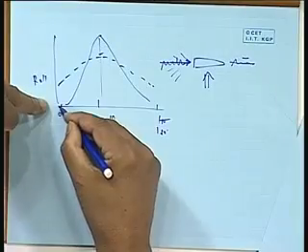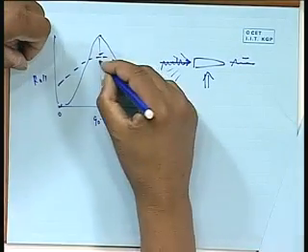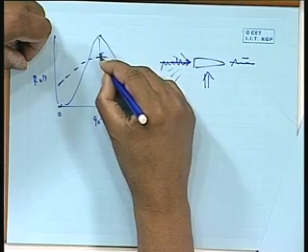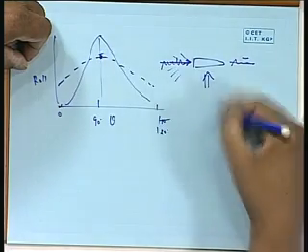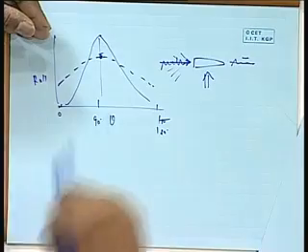So even though waves from that direction do not give roll at 0 degree, because there are waves from other directions, it will give you some roll. On the other hand, it gets maximum roll because of all the waves at 90 degree, but now here it is not so many waves at 90 degree, they are spread, so it will be less, so it will look more spread.